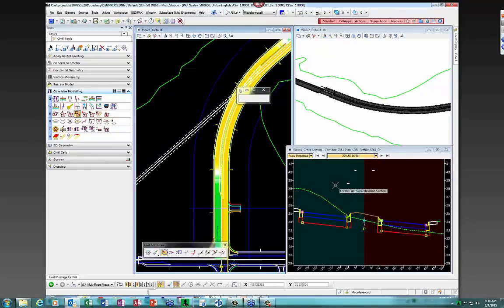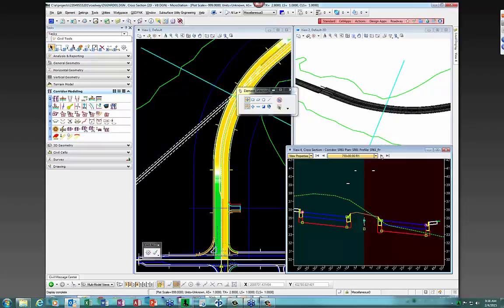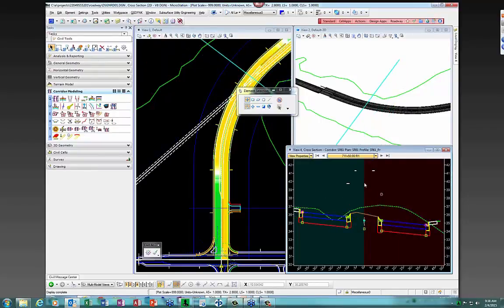Okay? So then I can just click out of this command, and you see that, in fact, I am now superelevated at that same station. And if I look, I'm in the middle of my curve here, and I'm rotating about the center point, because that's the method for which I set the superelevation up. So that is essentially the method for doing the centerline pivot.